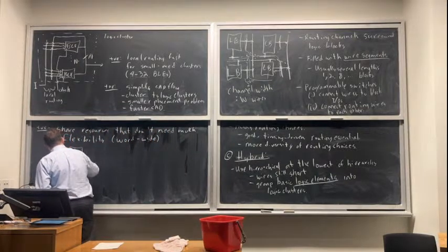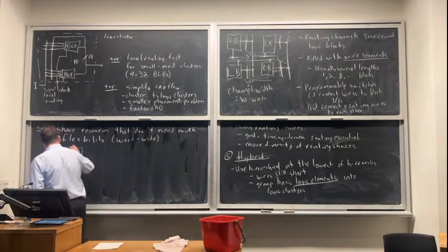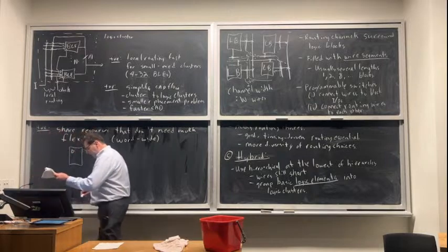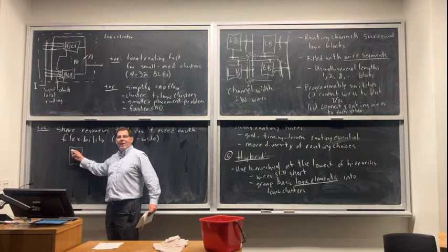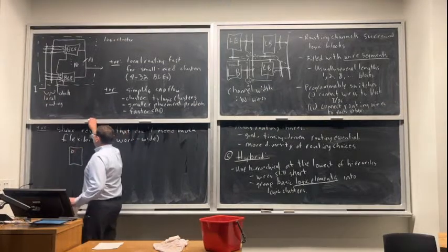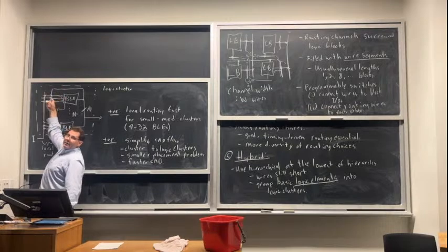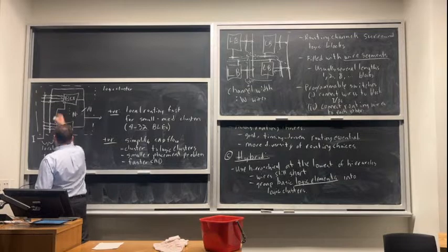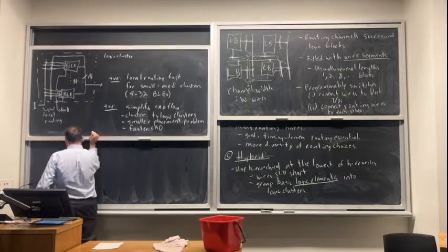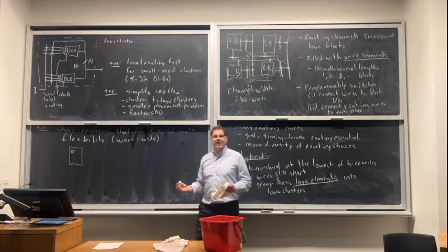So a lot of the signals that go into flip-flops are control signals. I got a flip-flop, it's got a D signal. Every flip-flop tends to have a different data input. So this would not be a smart one to share. The D input to the flip-flop is going to come from this local routing with a whole bunch of switching. So I have maximum flexibility, and every single one of these can pick a different D input. If they're all picking the same input, why do I have all those registers, right? I should just have one.